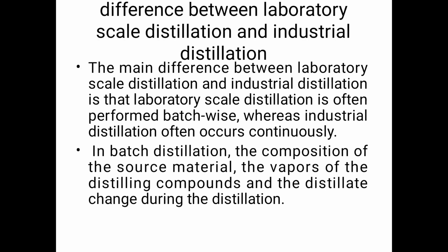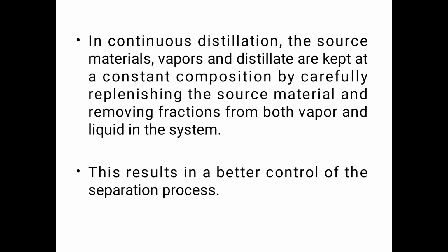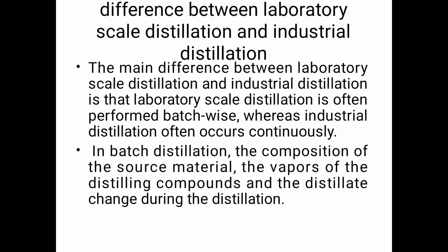The liquid mixture is heated to create a vapor. All the vapors formed are condensed in a condenser. A part of the condensed liquid is returned to the distillation system as a reflux and the remaining part is withdrawn as a product. In this method, liquid and vapor are brought into intimate contact a number of times and almost pure product can be achieved.